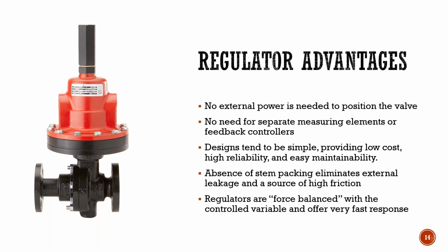Absence of stem packing eliminates external leakage and a source of high friction when you're stroking the valve. And regulators are force balanced with a controlled variable and offer very fast response. These respond off of the line medium itself. So again, respond very quickly to changes in the system.